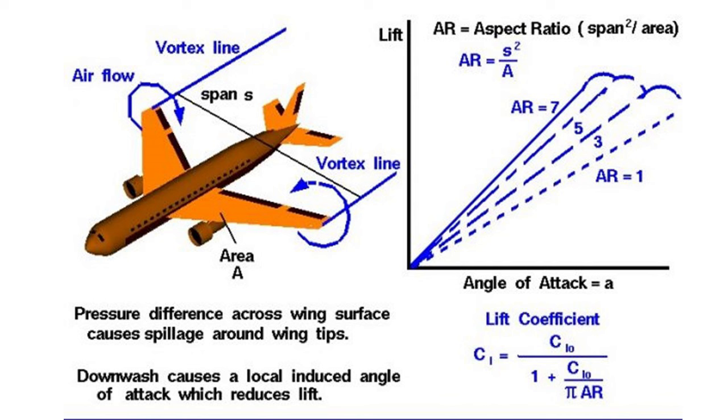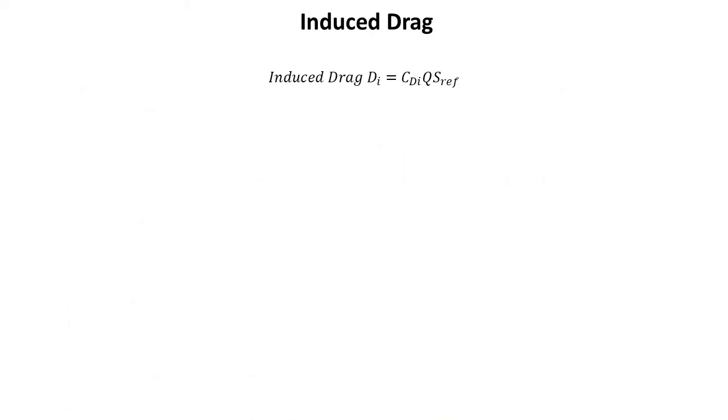Now remember that nothing is free in flight, and that by producing lift we must pay a price. So our job as engineers is to get creative and find some way to minimize this energy loss, because losing energy by imposing any unnecessary motion in the air that we're moving through, which in this case would be a vortex structure as a consequence of lift, is a huge waste. First, let's quantify induced drag so that we can properly investigate which parameter should be hunted down and either increased or decreased until our induced drag hits our target decrease.